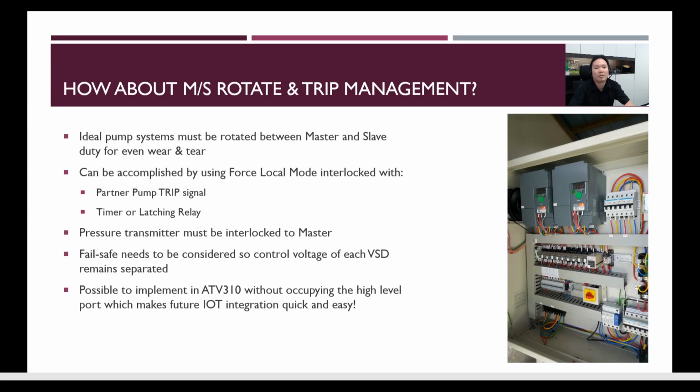Next, how about your master-slave rotate and trip management? For example, I have one inverter as a master and one inverter as a slave. I need to rotate them so that they have even wear and tear. If not, the master is always going to try to run first, and we have a situation where the master pump needs so much service, whereas the slave is just sitting there doing minimum work, which is not ideal in terms of maintenance.